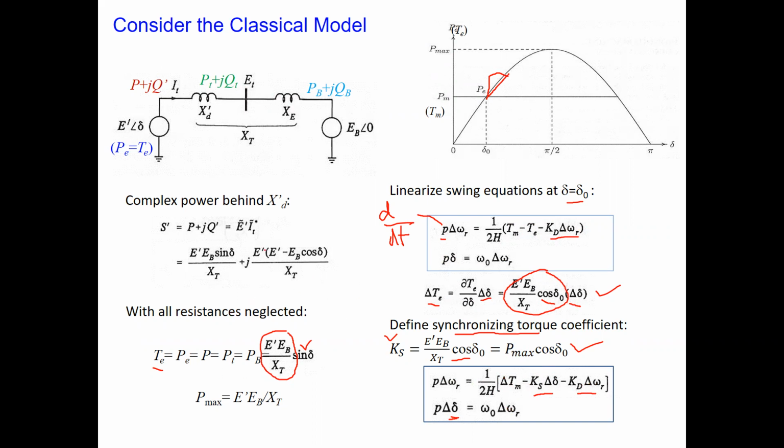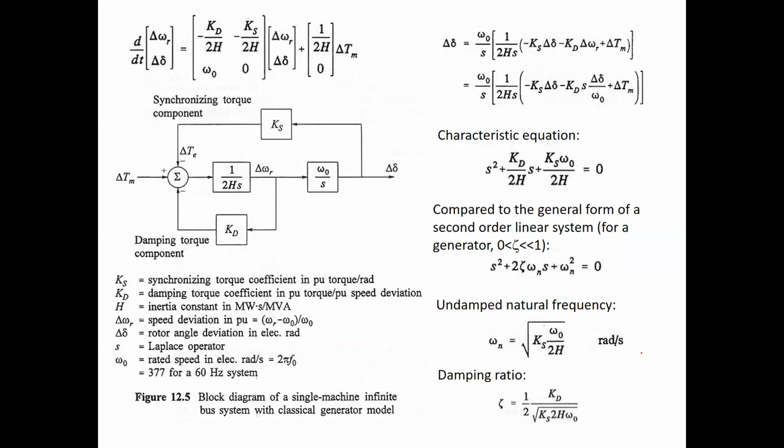We have the nonlinear equation here, and this is the procedure to linearize. That means to linearize, you just do the partial differentiation around the steady state point. This is the procedure to linearize any equation here. Right. Anything up to this?